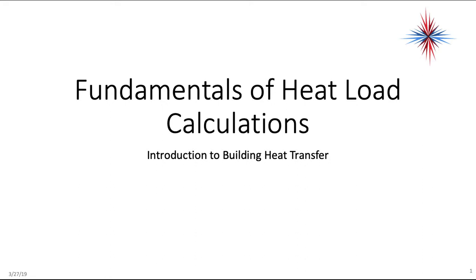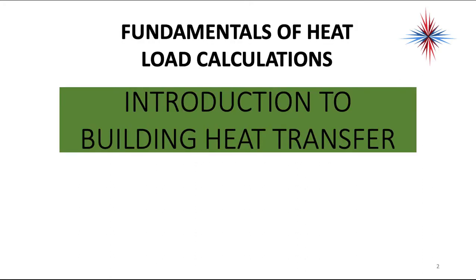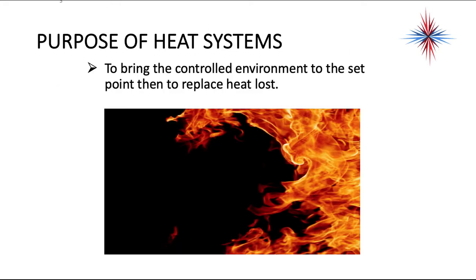Okay, the reason we talk about heat load in an air conditioning troubleshooting course or in a heating troubleshooting course is that we need to take a look at: is the system correct for the building? Was it installed with the right sizing? Will it actually heat and cool the space properly? Or what do we need to do to get it to heat and cool the space properly? The fundamentals of this is you have to do a heat load calculation. And you have to understand the numbers if you're using an electronic tool to do that heat load calculation. So let's start by taking a look at the building heat transfer.